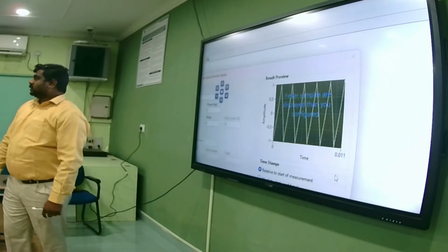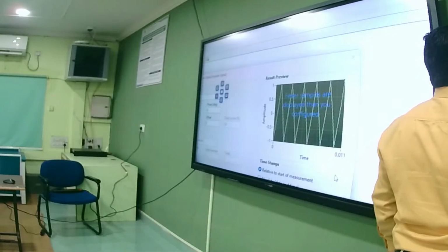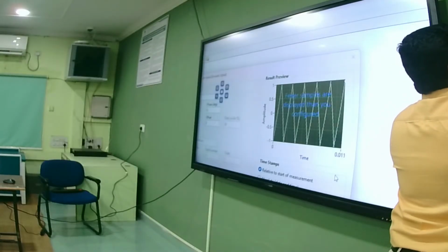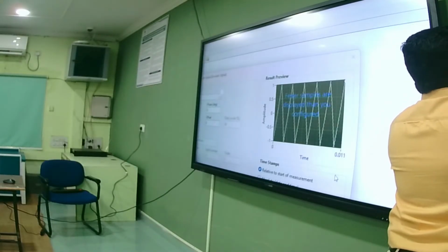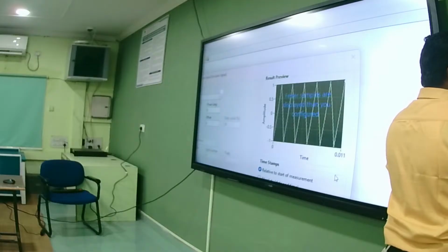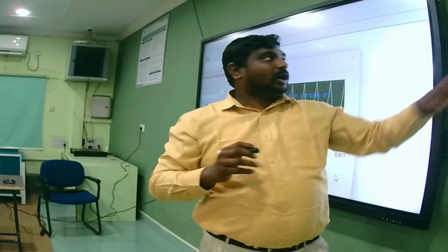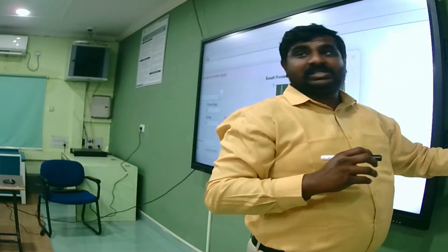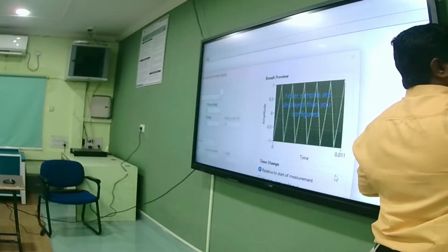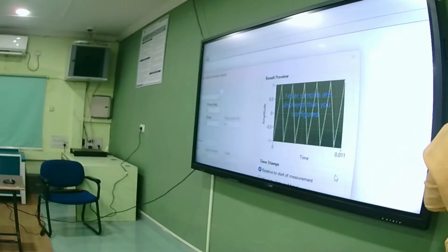Triangle. Because for one cycle, you have 1,000 samples per second. So frequency is 500 and sampling rate is 1,000. Exactly half. Yes or no? For 500 hertz, with 1,000 samples, for one cycle you can take only 2 points. For every cycle, you will take only 2 points.